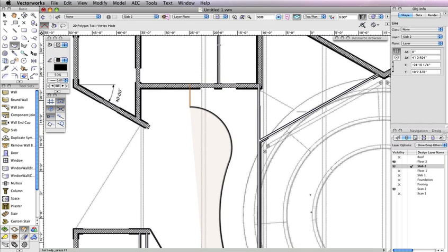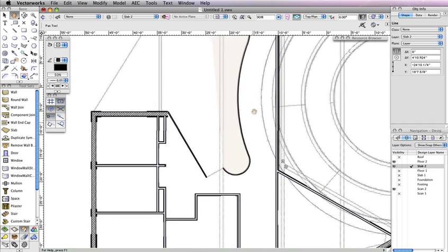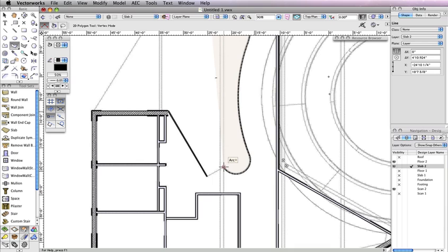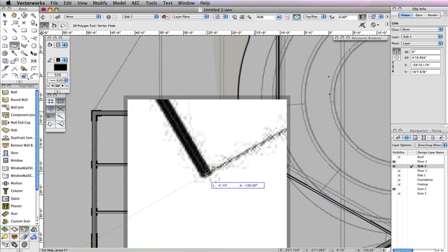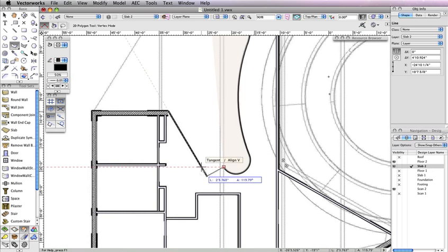With the Polygon tool still active, click on the bottommost endpoint of the curved polygon, and then follow the straight line that is connected to the curve in the scan layer. After the cursor cue 30 degrees appears, click somewhere near the end point of the line to match the scanned layer. Now, double-click the inside endpoint of the wall located to the top left of your current point.